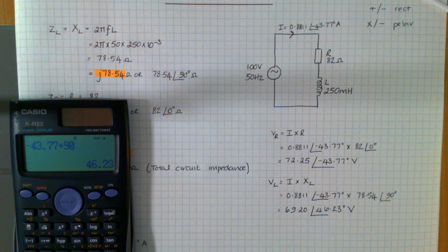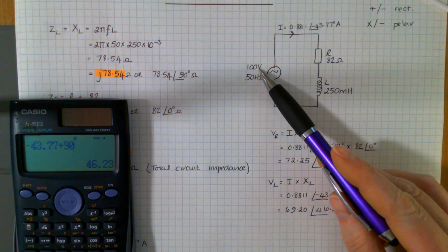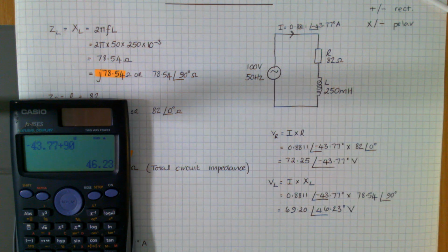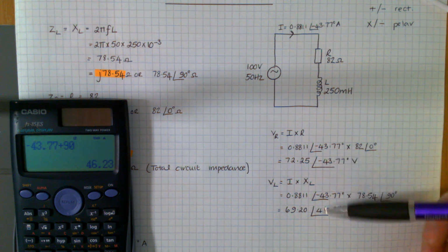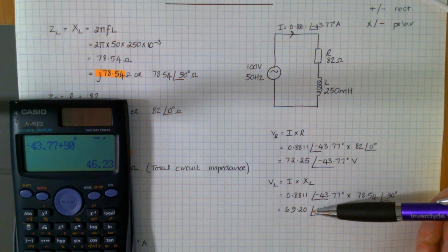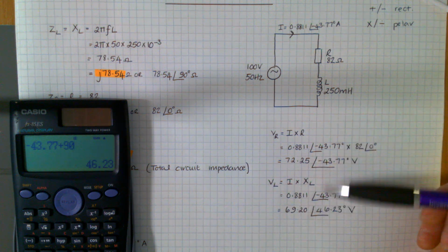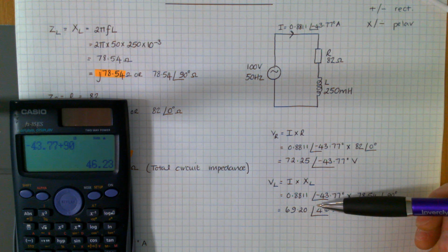Now usually, if this was a DC circuit, you would just add these two up and you'd say, well, these two added up gets you that number there. It's correct, that's all fine. Because these are done as phasors, we don't really know if these two add up to get us this. We can check by converting these into rectangular numbers, or we can draw the phasor diagram and check from that. So I'm going to draw the phasor diagram and check from that.